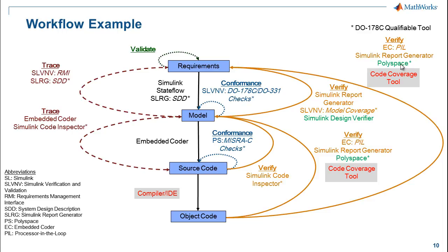Now, in a workflow like this, not only is it important to do that kind of analysis, but one of the nice side effects that you get is, because of how Polyspace does the runtime error analysis, it calculates the theoretically possible range of every variable at every operator in your source code. So what that means is that you can take those ranges and use that and exempt yourself from having to do the traditional boundary value testing that you might otherwise have to do.